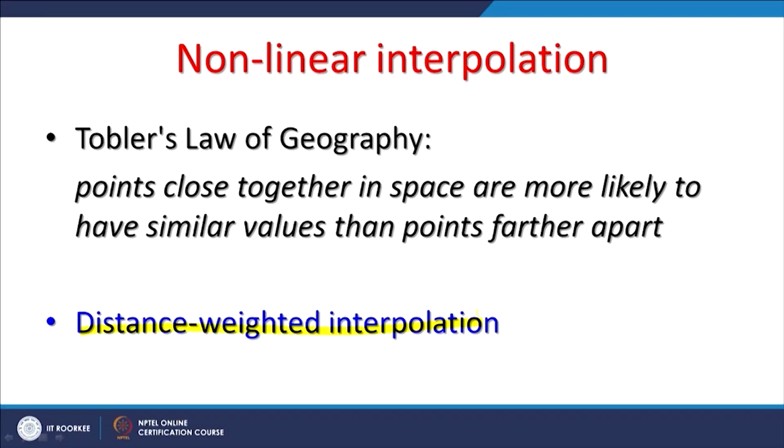So, if interpolation has to be done for an unsampled site, then among the input points, the point which is closest will have the highest weightage, and the point which is farther will have less weightage. This is what is called distance weighted interpolation.